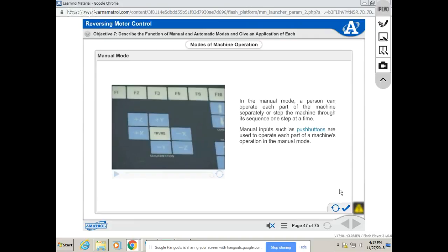So in our door example, in automatic mode it would stop at the limit switches, but in manual mode I could just run it until it tore up. That's not always the best deal for a machine, to give the option for manual control that can tear it out. So it's similar to a jog. You hold the jog button down and the machine will run until whenever, till it breaks or gives. A lot of times they do that for clearing jams in some kind of feed process. That could be good or bad. Hopefully the overload trips before it tears up something.